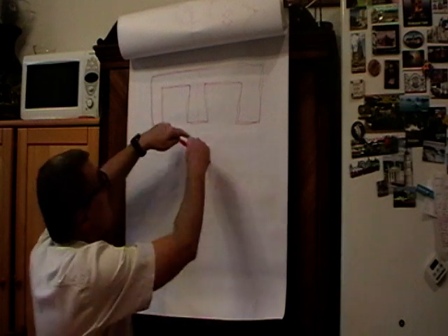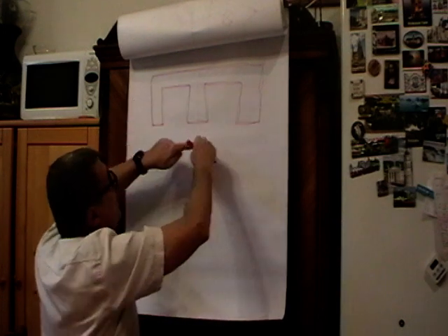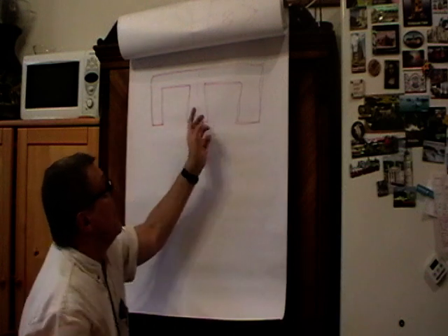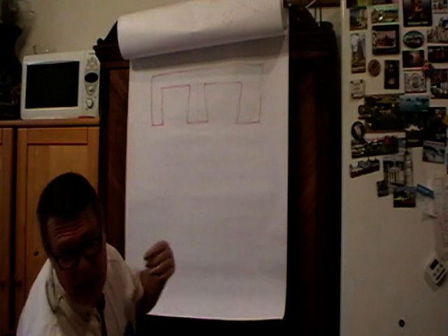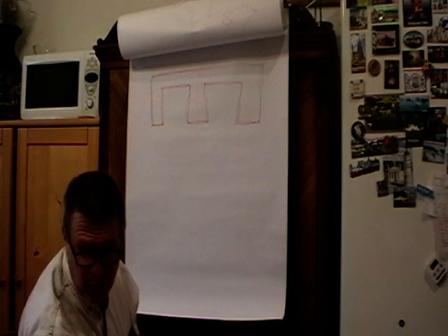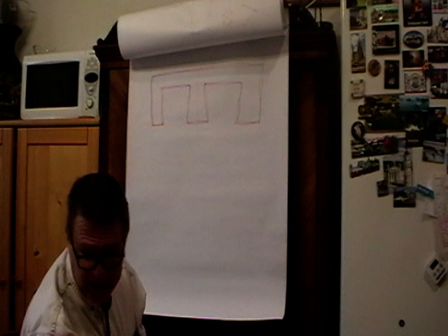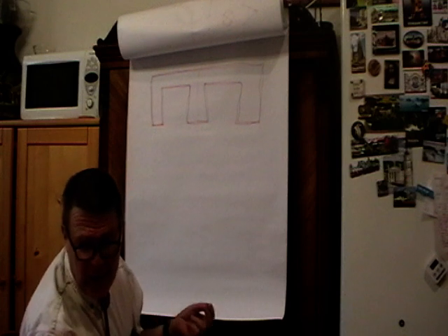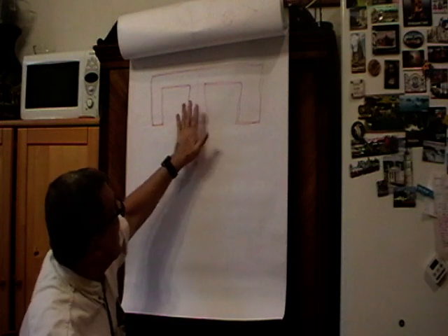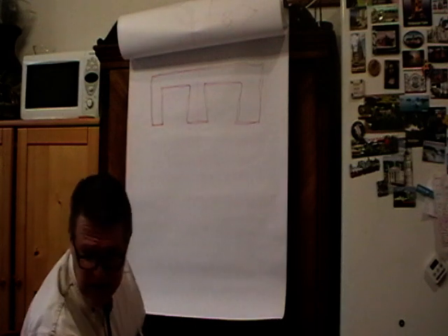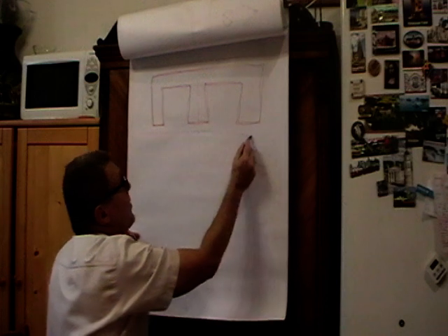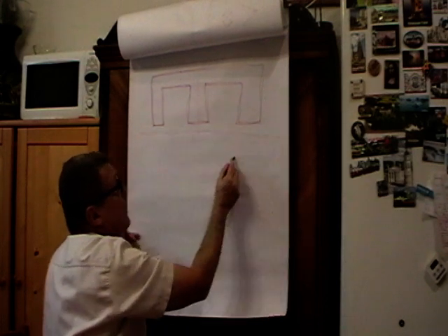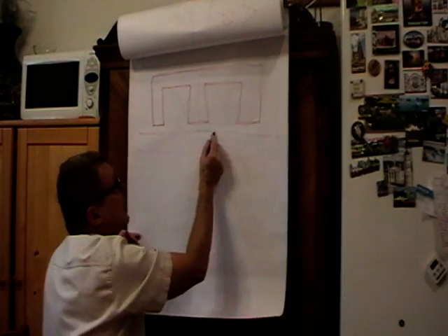But as the magnetic flux flows this way, the magnetic flux in this part is doubled, and in order to keep the saturation far enough, the width is doubled in the central part. So this is the E shape of the magnetic circuit. And you have the rail under that.